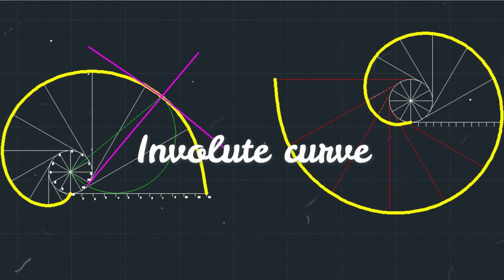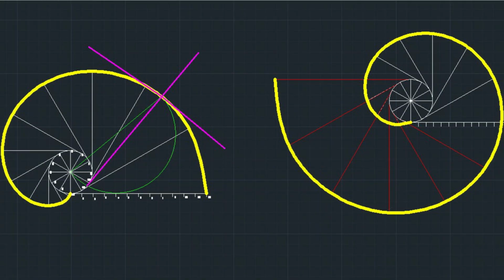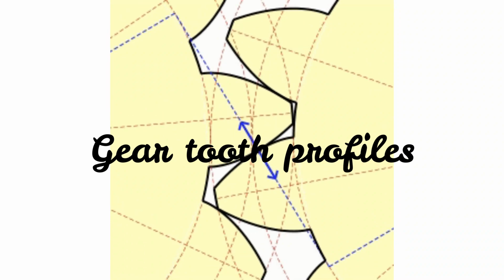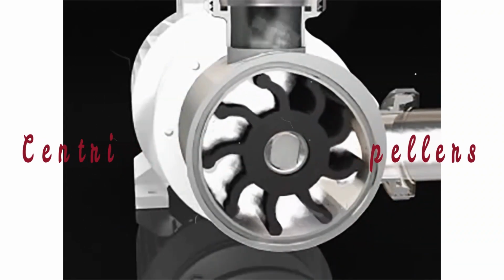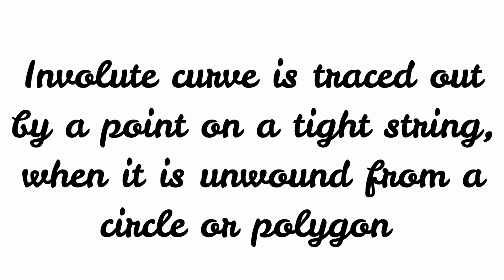Here we are going to see the involute curve. Involute curve is mainly used in designing applications like development of gear tooth profiles, designing of centrifugal pump impellers, etc. It is defined as the curve traced out by a point on a tight string when it is unwound from a circle or polygon.